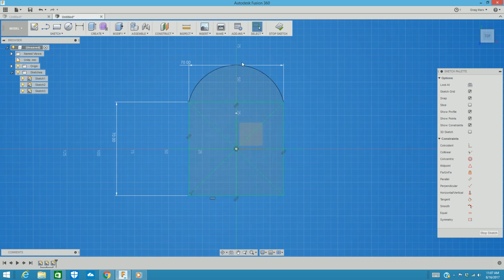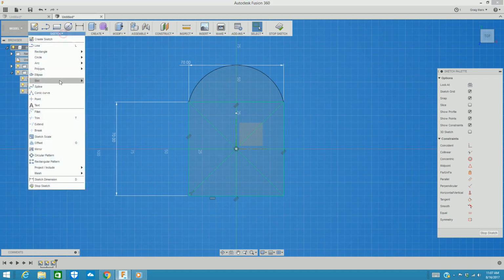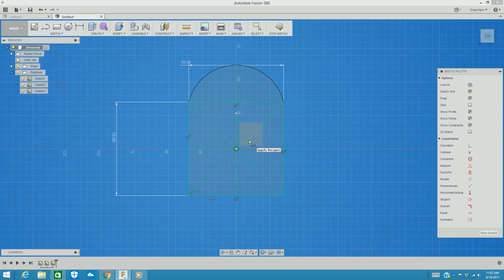And I know it's closed because, again, it changes color. But now I have 2 areas of this sketch. I have the square area, and I have the top that is rounded off. If I wanted to get creative and artistic, I can use a spline to make a curved shape. In the spline, you just have to play with it to figure out how to control it. But it's designed to be a line that bends, and it bends every time you use the mouse button.